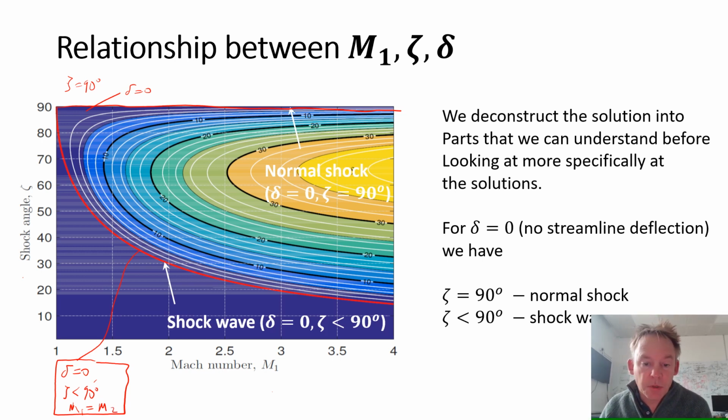So if we were given a Mach number and a deflection angle, a wedge angle, then we would take our Mach number, let's say Mach number 3, look at 20 degrees and find out where that occurs. What would the consequence of that be? Here we're talking about something like 38 degrees, the shock angle of 38 degrees. There are other tables, and you've been given those, or there are electronic versions of those on the Moodle webpage, and the ones we've used in the past for teaching students how to solve this problem.